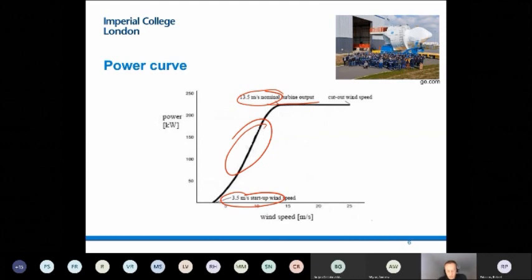So wind turbines are designed for rated power, and the expectation is that they operate in this regime for most of their life. Now, wind can get very strong, and when the wind gets strong enough, you end at a point which is called the cutout speed, beyond which the wind turbine actually is stopped. It's unsafe to keep performing. Of course, this is something you wouldn't like to see, but the reality is that you need to put limits to any design, otherwise it will be unfeasible.